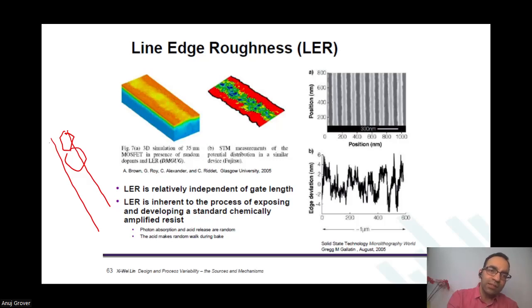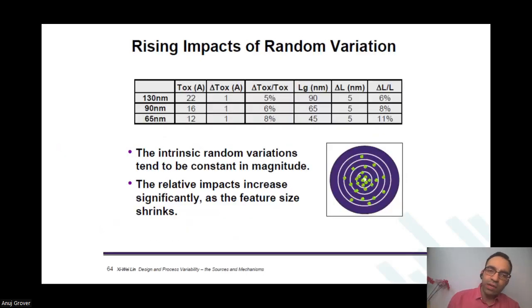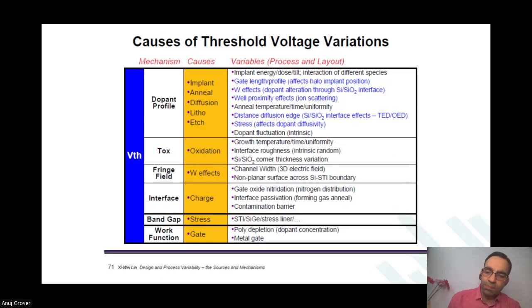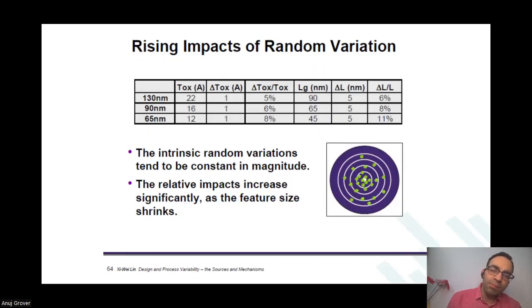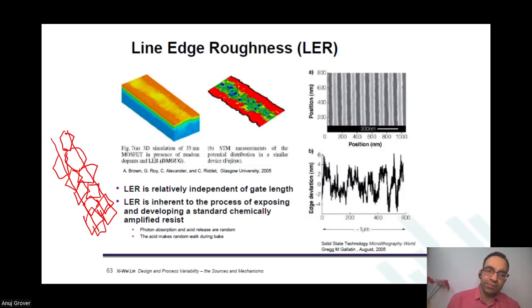So let us take this example. Let us say that there are these different crystals of silicon dioxide that form the poly region over here, and so on. So when you started to etch, what happens? At the crystal boundaries, the extent of etch changes.